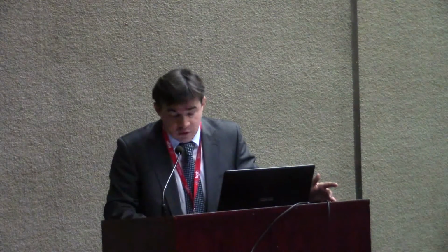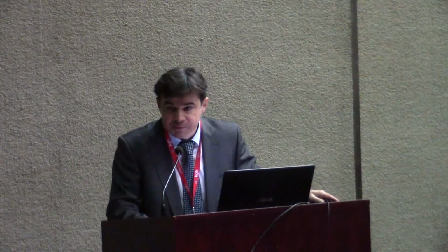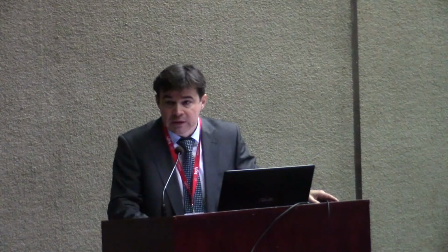For input, after that there are variations in airflow and also in temperature, and we can see on this slide disposition of air temperature: 40 degrees on the floor, and temperature decreases up to the height of the building. Also disposition of air velocity. And conclusion, there is potential danger of condensate generation beginning from 10 meters from the floor.